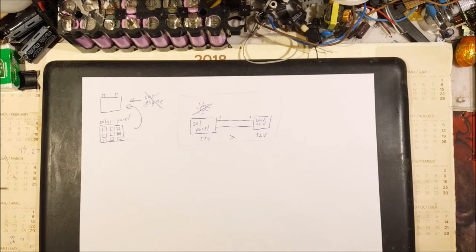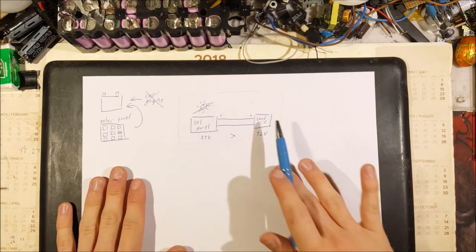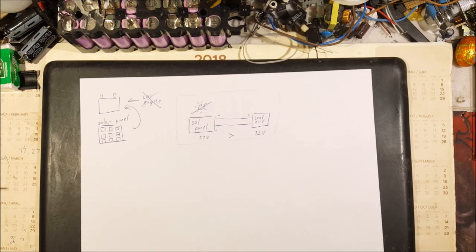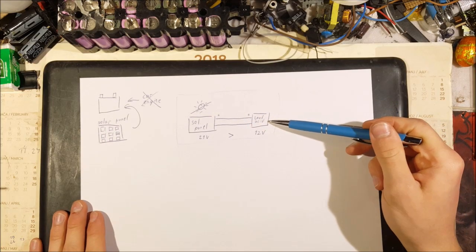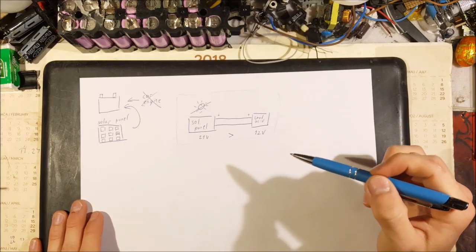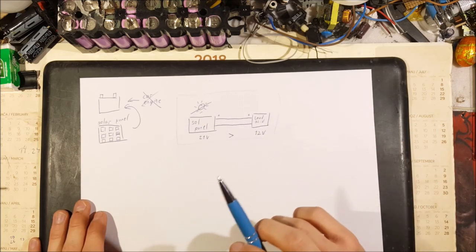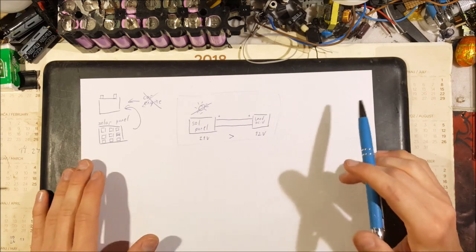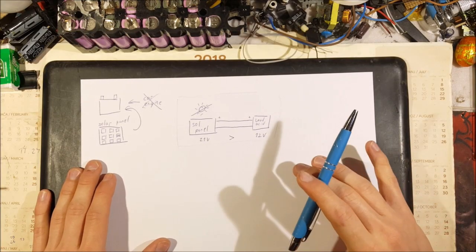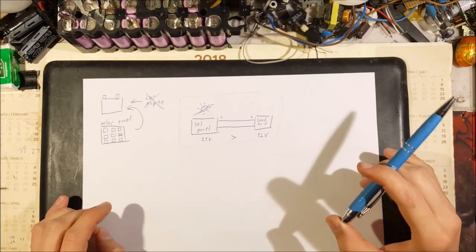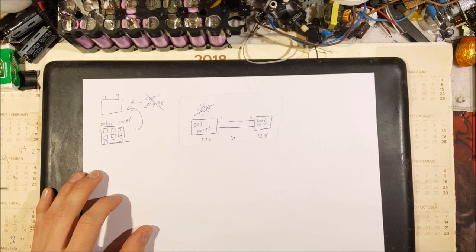Well, that's where you are actually wrong, because there is something in the circuit limiting our current. Now, it sure as hell isn't our lead acid battery, which has a few milliohms of internal series resistance. It won't be our cables, because a good quality copper wire won't drop more than a few volts unless it's way too long for its purpose or way too thin. That leaves us with the solar panel.